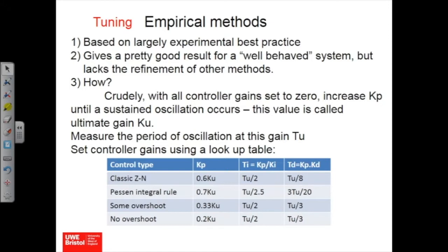Okay. These are expressed, by the way, you'll see that I've got Ti and Td here. Lots of people describe 3-term controllers. The Kp is always the same, but it describes the integral and the derivative terms in terms of time. You can see the relationship. Integral time is Kp upon Ki, derivative time is Kp upon Kd. And you look up the recipe book. And it will give you, so long as the system is reasonably well behaved, it will give you a reasonably good result.